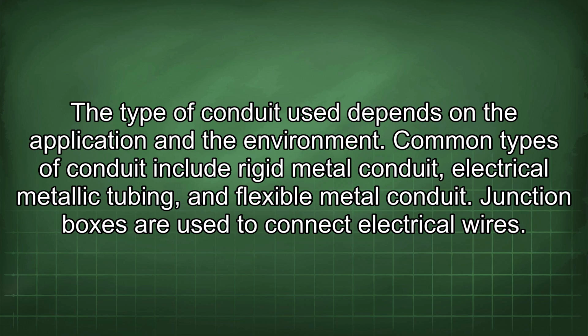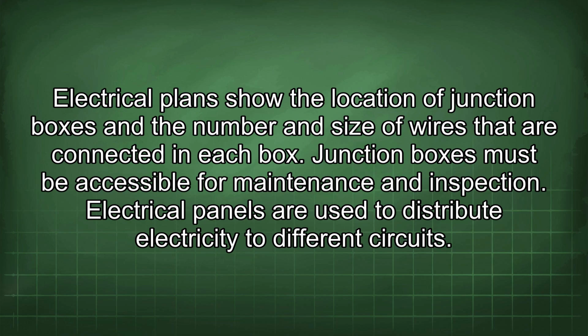Junction boxes are used to connect electrical wires. Electrical plans show the location of junction boxes and the number and size of wires that are connected in each box. Junction boxes must be accessible for maintenance and inspection.